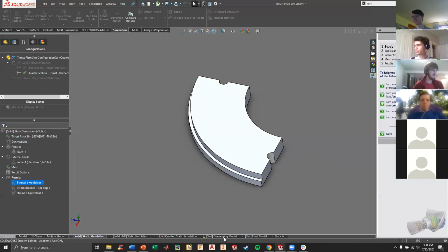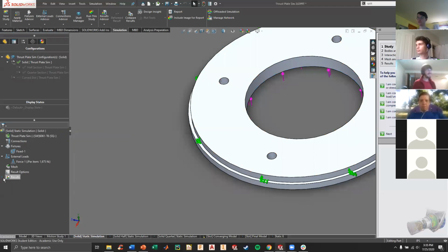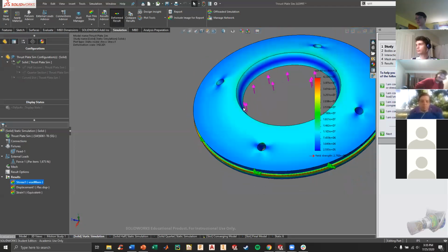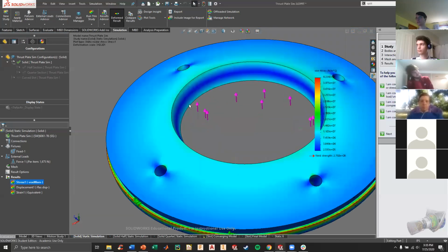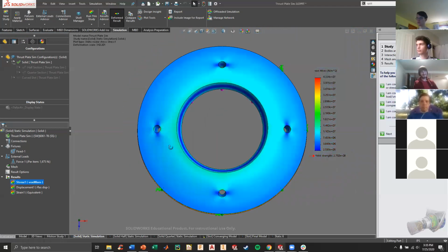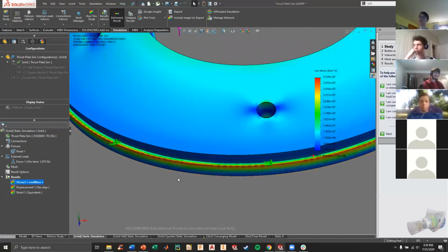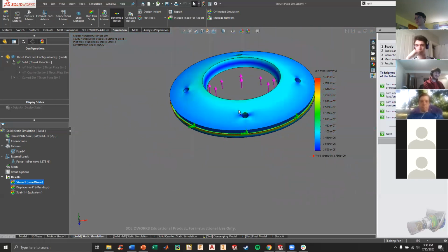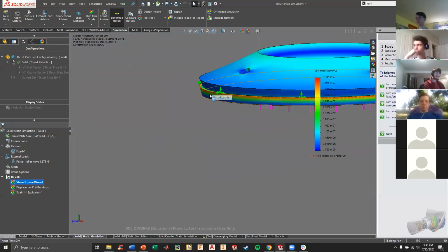But something that is super important to know is how to know if your results are accurate. So I have this result here. I have my stress and I have my displacement. And you can sometimes say, yeah, that makes sense. Like it should be pushed up in the middle. It should be solid on the sides. You could say that the stress kind of makes sense. Like this is where it's fixed. This is where it's not going to move. So there's just going to be a lot of stress on this point. But really, we want to ensure that this result mathematically is an accurate one.